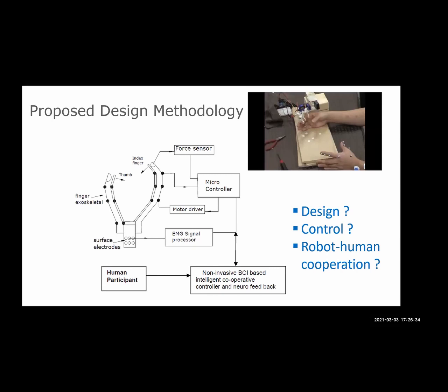So in the design of an exoskeleton for the fingers is something like this. So essentially, we have a mechanical structure on the fingers, which is actuated either by EMG, EEG, or by taking signals from the other hand, which is not impaired. So in this case, we have put markers, and using a vision camera, when the person moves the good hand, the impaired hand also functions. Okay, but we want the person to focus, and hence the question of BCI. So first, I'll talk about mechanical design of such systems, and then we'll go on to the controller part.